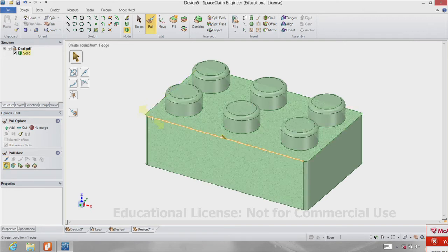The top edge, we're going to have a look at doing something called chamfer. Now last time I went round and I selected each edge one at a time, like that. Yeah, just went round and chose the edges. If I double click on an edge, it tries to pick up all the edges associated with that single edge. So in one clean go, so let's do that again, double click, I'm able to select that top edge.